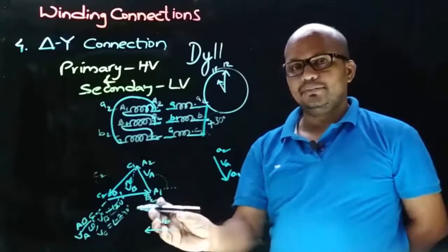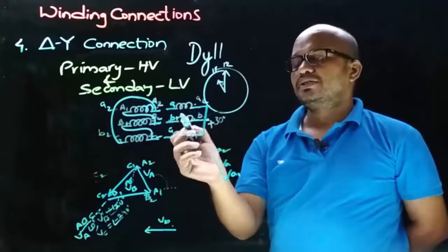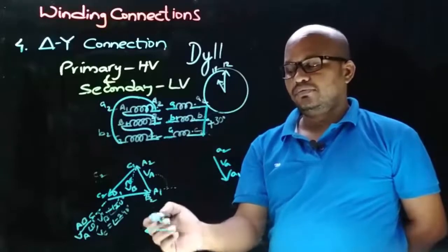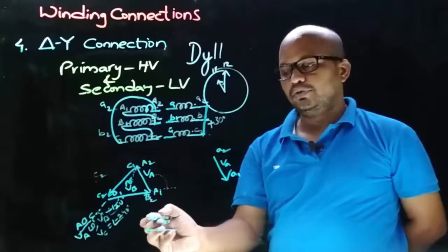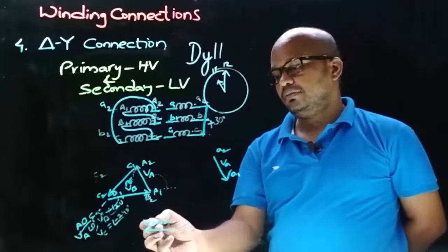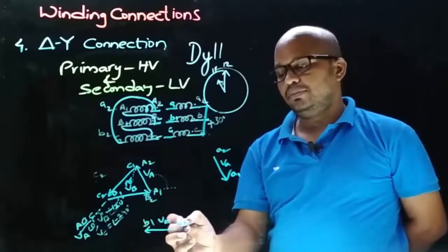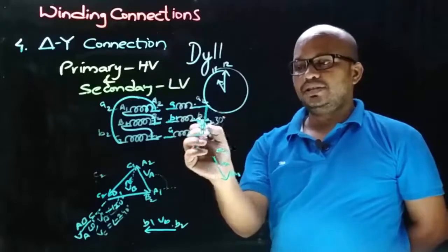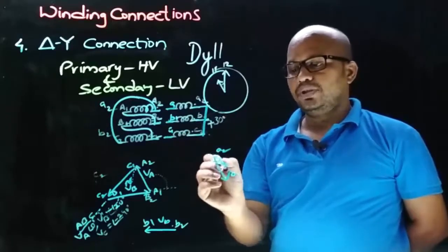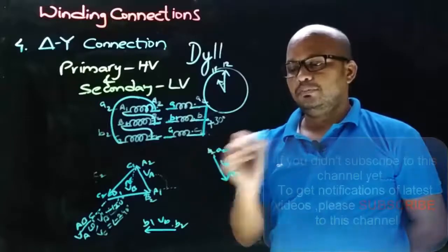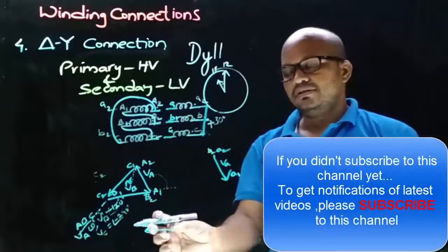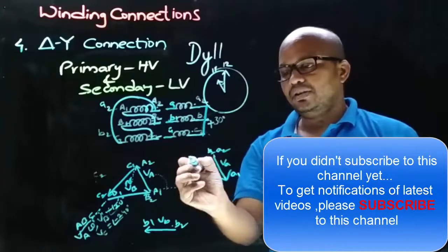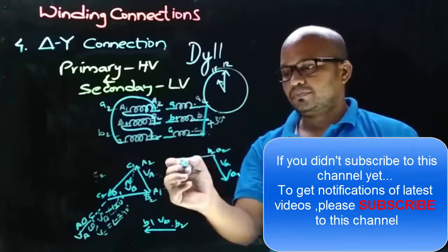Now let's decide the terminals of the secondary side VB phasor. As the connections are taken from non-dot end terminals, the arrow will point towards the connection we took from, that is here B1. Therefore, the other end will be B2. And observing the winding connection, to A2 terminal there is B2. Therefore, to A2 we will have the B2 connection. So draw this secondary side VB phasor such that the A2 terminal will have B2 like this.